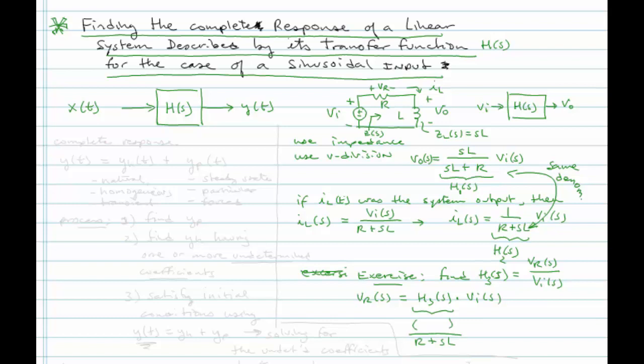And there's really only so many transfer functions you can write for this network because it's a very simple system. But this is a characteristic of linear systems, and that is that no matter what transfer function you express to relate the input to some output, you will always have the same common denominator. And that is because the denominator actually is the characteristic equation of the differential equation that describes that system.